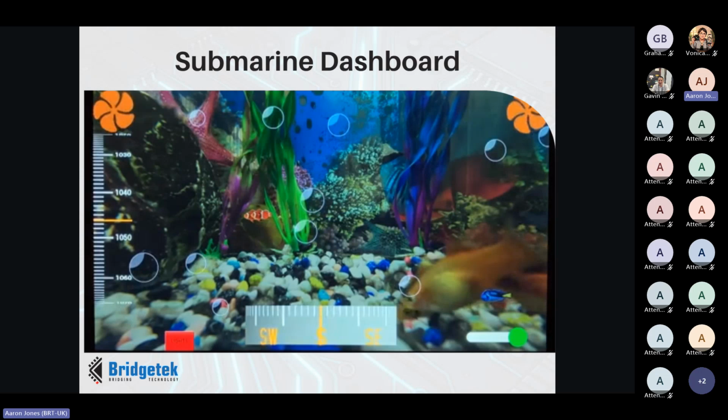The BT820's live video input allows us to use the live camera feed from the ROV to be displayed without passing through the MCU as a full or partial screen overlay. In this instance, we're using a full camera feed and overlaying gauges on top. Bespoke indicators for heading can be smoothly animated on top of the live video engine, as you can see here, as well as touch controls for the lights, for example.